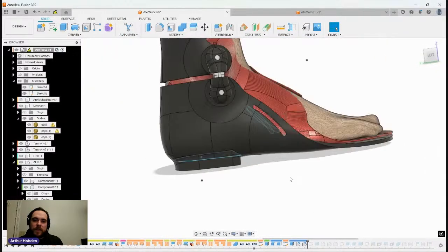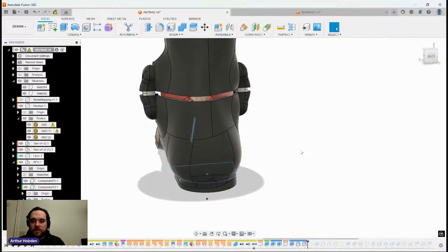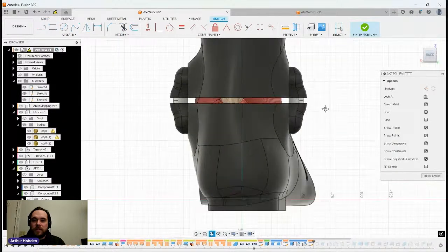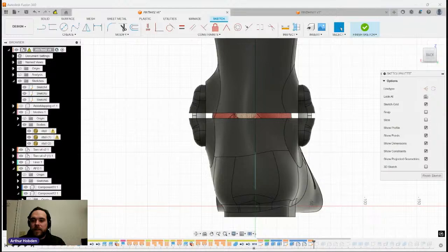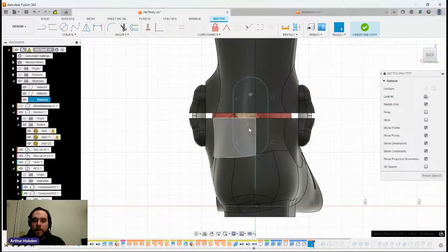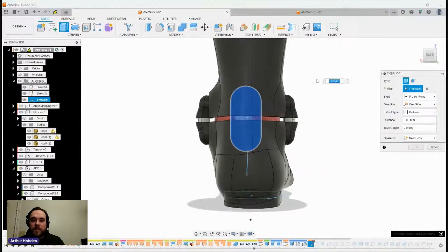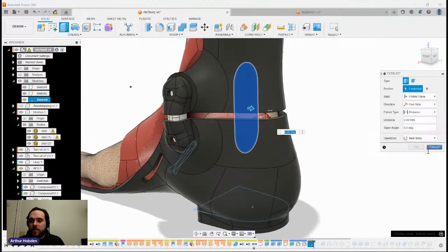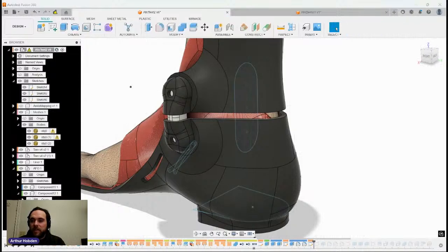So there's that piece. Finally, we can do a stopper on the back, which is also another common feature. So what if I created a center point slot from here to here, going straight up and down, something like that. And we're just going to throw that down. We can dimension this or make that as relevant as we can. So I'm just actually going to split a face.